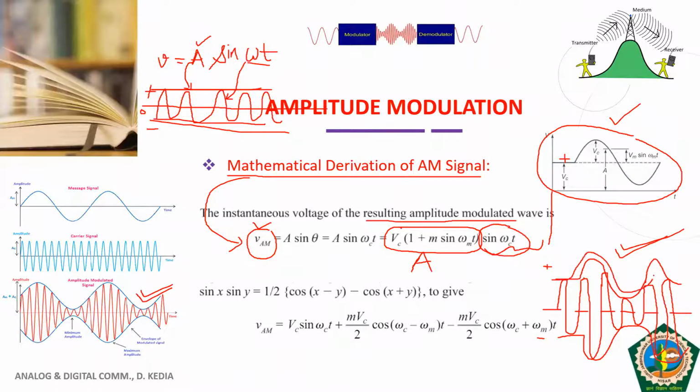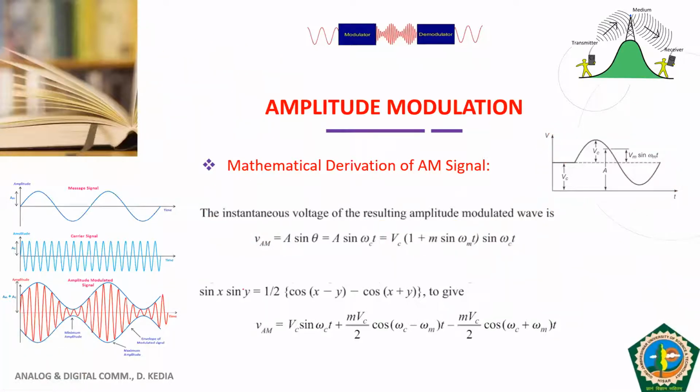This is your amplitude and its mirror image. If you draw this equation graphically, you'll get the same kind of thing, and inside you have the carrier. If you want to look at it more precisely, you can look at this waveform. Here, this is the positive part of the AM signal. This is its mirror image on the negative side. In between, we have drawn the carrier wave touching all the contours of your amplitude. If I erase it, you'll be able to see it.